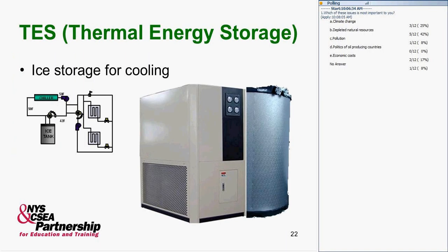Okay. Tied into that, thermal energy storage. It's about as simple a system as you can go with. You make a giant vat of ice all night when the electricity's cheap, and you run air or water through that ice and use it to cool the building off all day. So you pay less for electricity because you're using it at night.